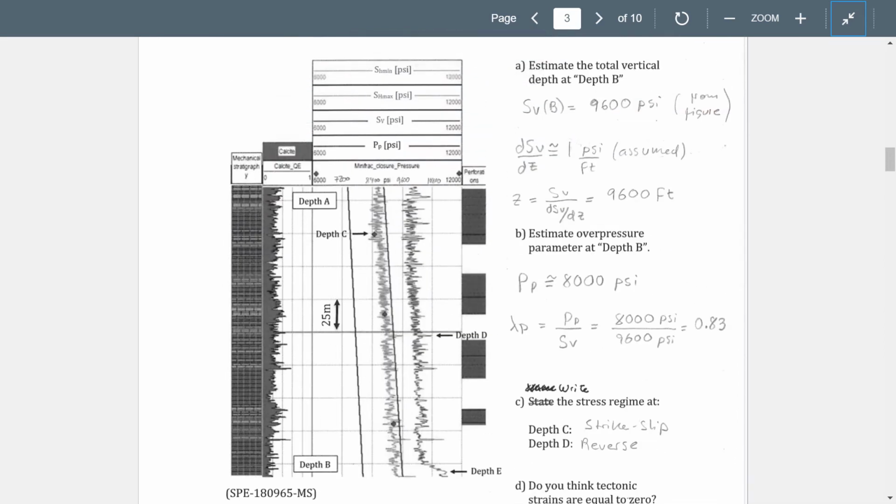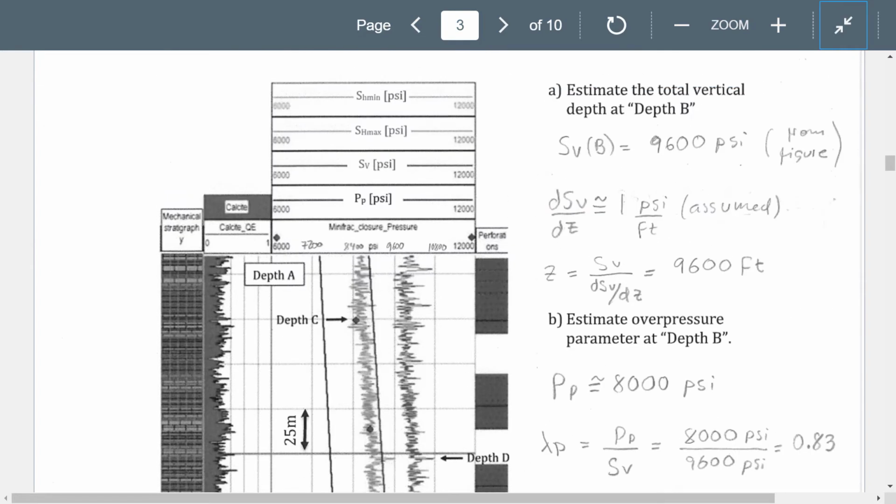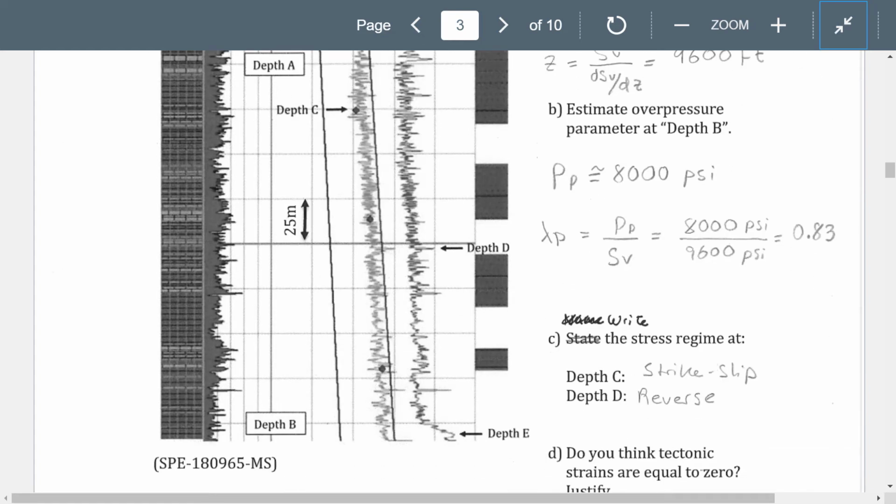Okay, so in this problem, this is a stress log. These stresses will be figured out the same way that we're going to see now, but with a more complex mechanical model, assuming anisotropy and a few other things. But this is our ultimate objective: in the same plot, to plot pore pressure, vertical stress, and the horizontal stresses. And with that, if we know where the perforations are going to be, or actually where the perforations are going to go in order to fracture the intervals we're interested in, we can determine what the fracture height is going to be.